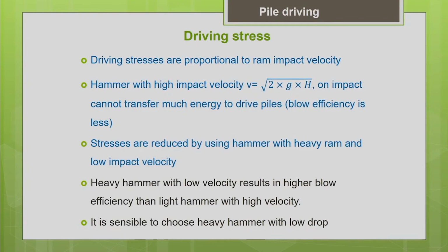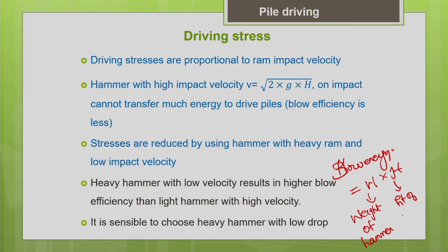Another important guideline to keep in mind to control the driving stress is that the driving stress will be very high when the impact velocity is high. That depends upon your height of fall. As everyone knows, the blow energy is nothing but the product of W into H, where W is the weight of hammer and H is the height of fall, or the stroke.